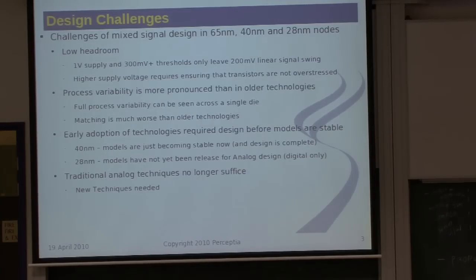But the net result of us operating at this small size is that statistics is breaking down. In the source or the drain, we're trying to make an N+ region by doping in specific atoms. If we've got a 500 nanometer process, there's a lot. In a minimum sized transistor, we might only have 50 dopant atoms creating this thing. A change of 1 or 2 in the number of atoms you put in there and your transistor has changed. So the smaller we get, the more.